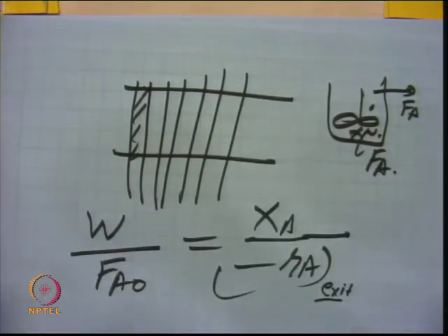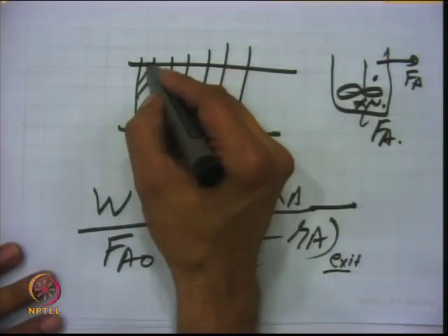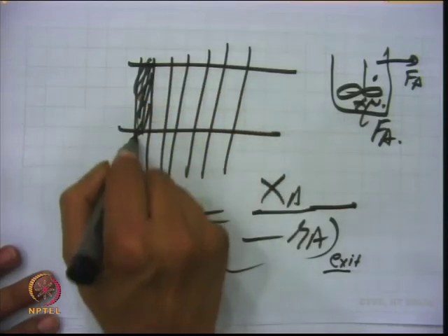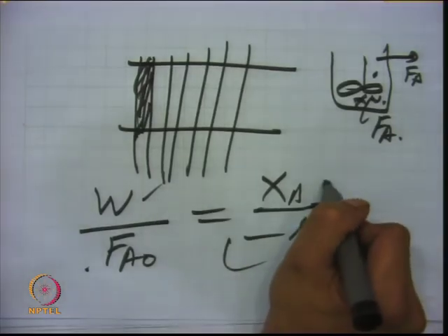If you have this case, I have assumed right now a differential plug flow reactor, which you have defined: F_A0 dX = -R_A' dW. At that time, dW becomes W, F_A0 stays F_A0, and dX becomes X.